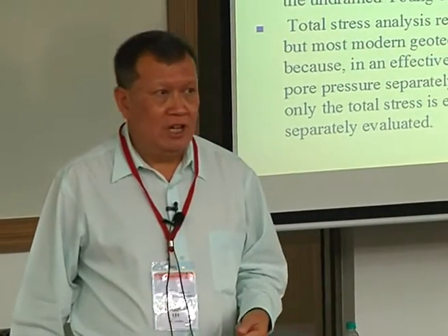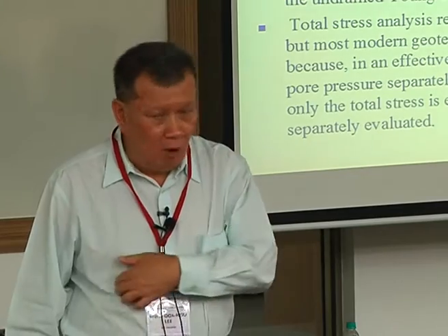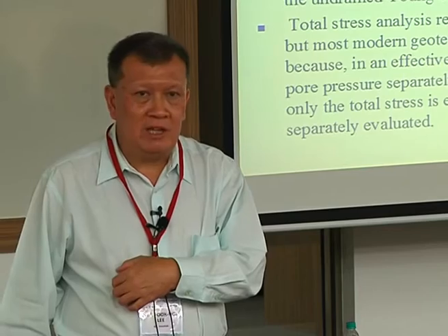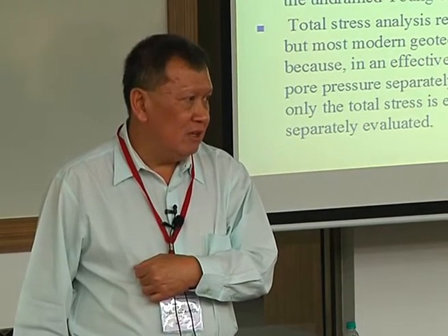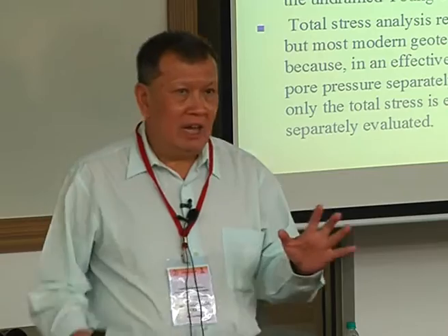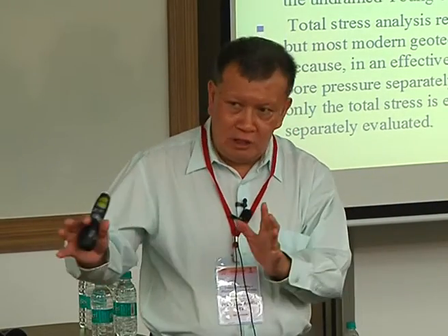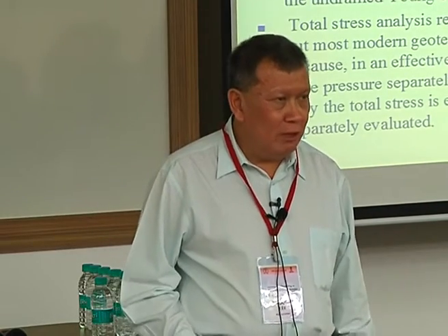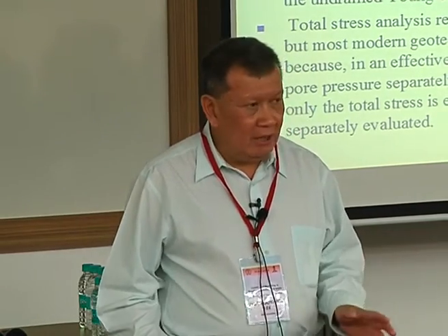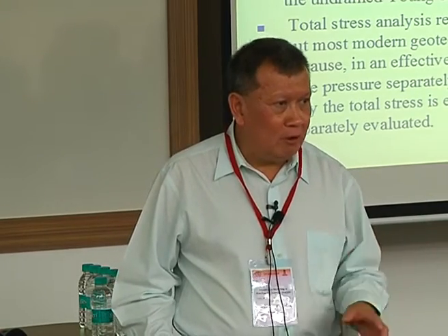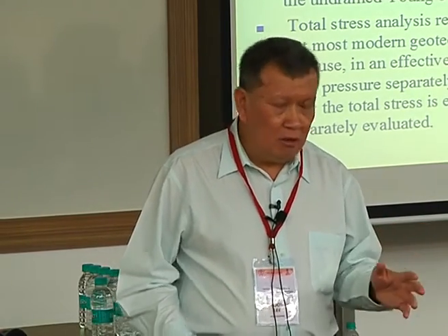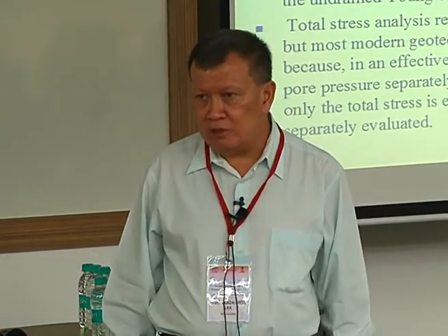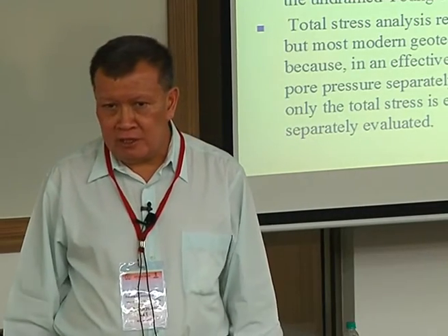But the other thing is, of course, if you want to run a very sophisticated model, anything more than Mohr-Coulomb, they are almost always expressed in terms of effective stress. Mohr-Coulomb has effective stress and total stress versions, but anything more complicated than that is always in effective stress. So when you use something more complicated, like the Cam-Clay, the Plaxis soft soil model or the hardening soil model, they are all expressed in effective stress. So you have no choice then but to use effective stress analysis.